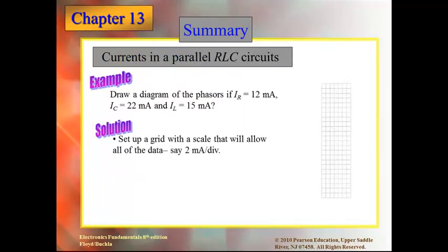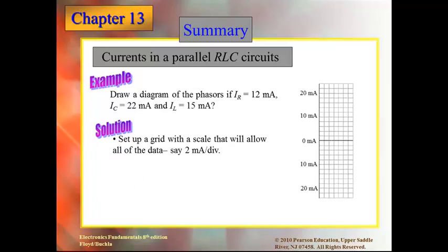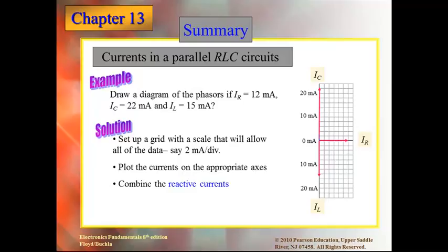And so here phasors, again, reminding us about our triangles. Move to a parallel circuit, so we can't plot an impedance triangle anymore. Parallel circuit, I always recommend you plot a current triangle. So, here they're showing current on the resistive leg of 12 milliamps, current on the capacitor of 22 milliamps, and current on the inductor of 15 milliamps. So then we can set up the grid and we can subtract again the 22 from the 15 and plot our Pythagorean, or plot our current triangle from there.